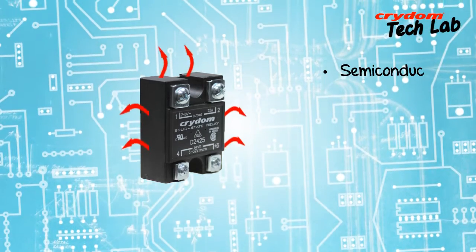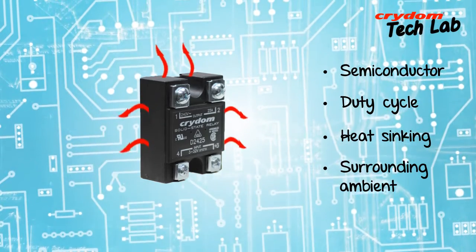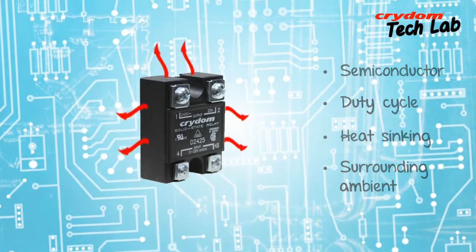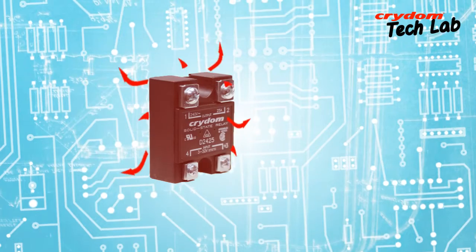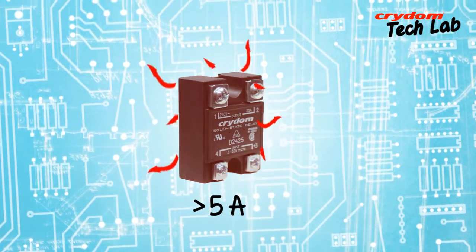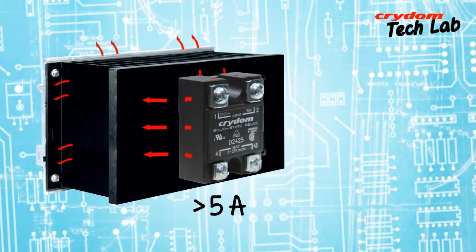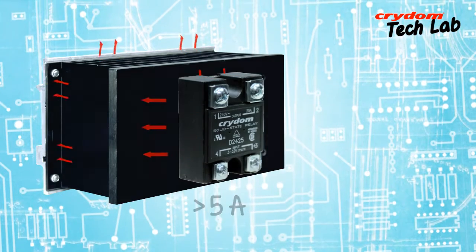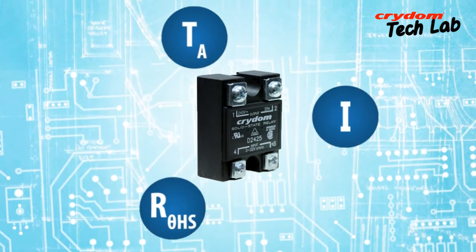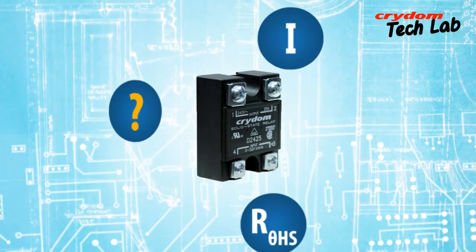Variables such as the type of semiconductor, duty cycle, heat sinking, and surrounding ambient all affect the temperature of the SSR or SSC, and therefore the load current allowed through the relay. Generally speaking, SSRs or SSCs carrying more than 5 amps of load current will require some amount of external heat sinking in order for them to operate correctly. During this TechLab episode, we'll discuss the relationship of the 3 most significant variables: load current, ambient temperature, and heat sinking, and show different methods to determine one of these variables when the other 2 are known.